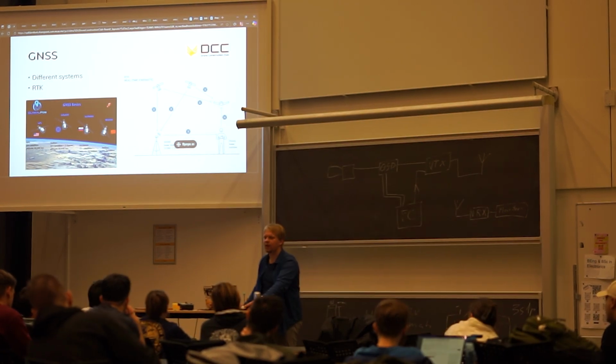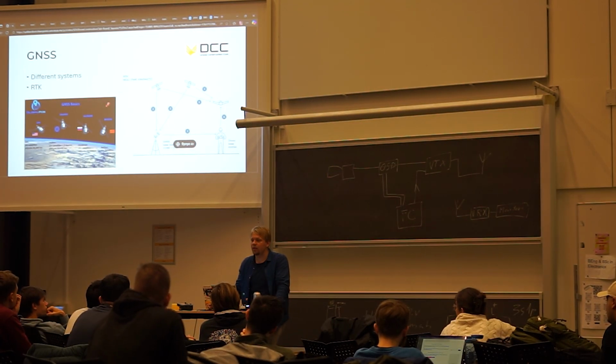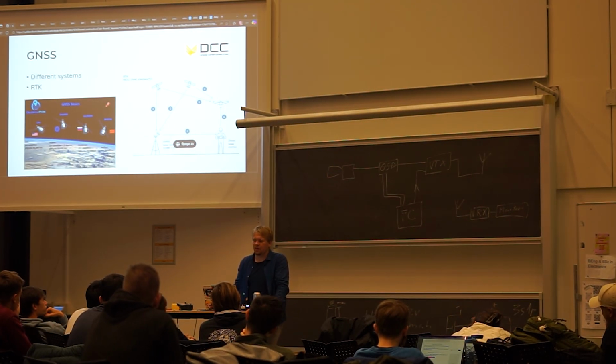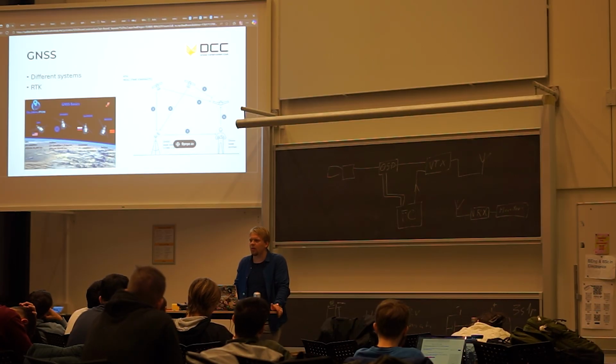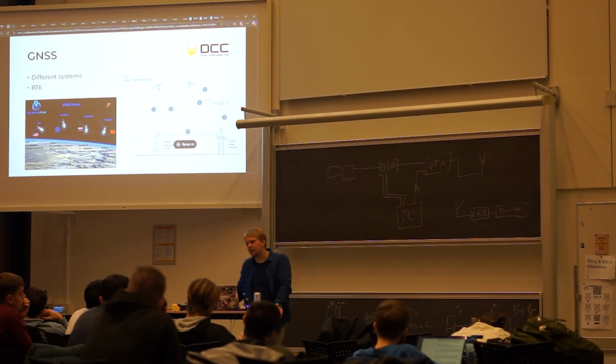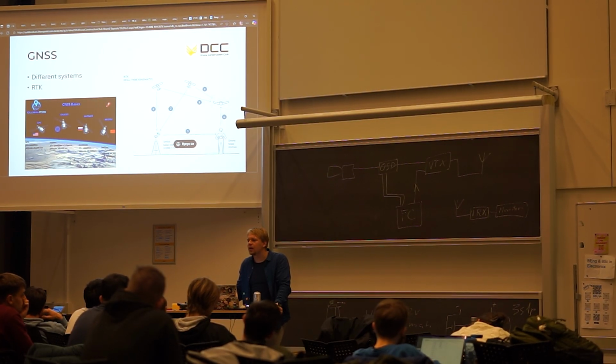Quite often they also come with a compass on board, sometimes with temperature gauges as well. And what they do is they just know where you are. That's it. You connect the UART for GPS data, and then you connect an I2C for the magnetometer data. Remember to reverse the UART wires, TX to RX, RX to TX, and you're kind of good to go.